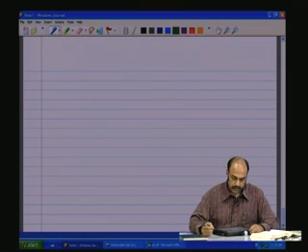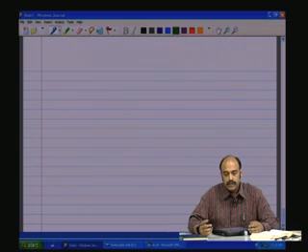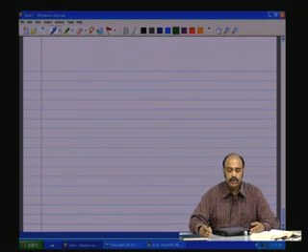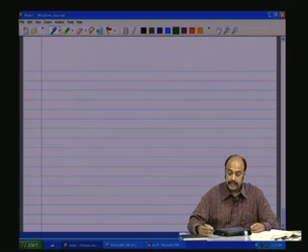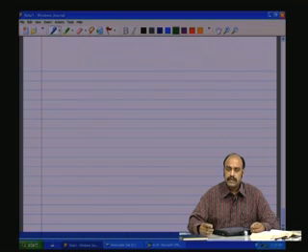Now there is one important thing that you should know. We saw that there are machines with different numbers of poles. You have the 2-pole machine, the 4-pole machine, 6-pole machine, 8-pole machine, 20-pole machine, and so on, for different applications. What is the maximum synchronous speed that one can achieve for a given frequency source? That is at 2 poles.